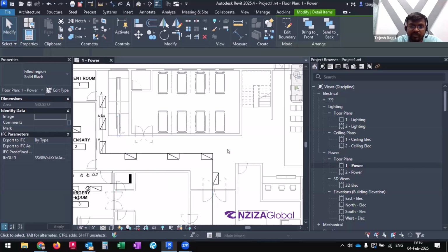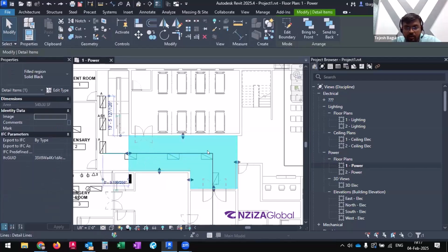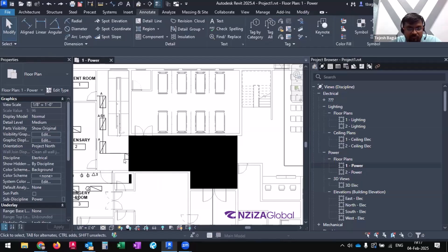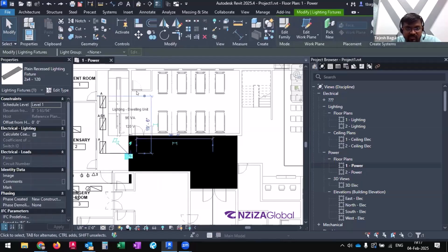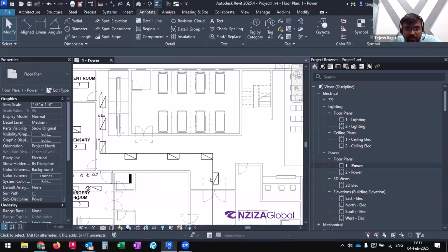What does blind spot mean? Let's say in that area we again calculate just one emergency light fixture, and since we had not considered this light fixture in this area and you use this as emergency, the path of egress at this point will most probably be downlit. There will not be enough light on this area.